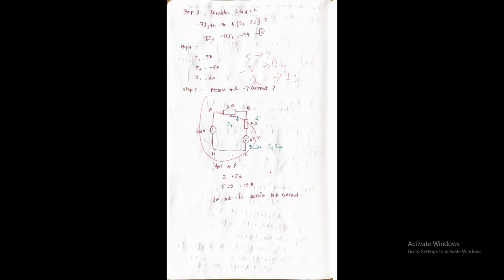So the current flow here is given by the equation obtained in the previous part, which means the values obtained for I1 and I2, the numerical values only, we are going to add to get the current flowing in the 4 ohm. Why do we need to choose I1 and I2? Because the 4 ohm resistor carries the additive part of I1 and I2.